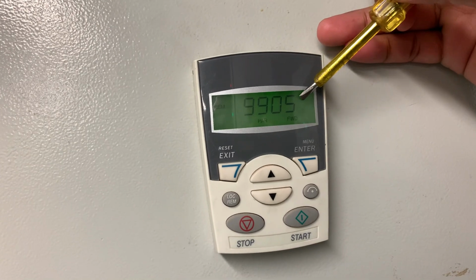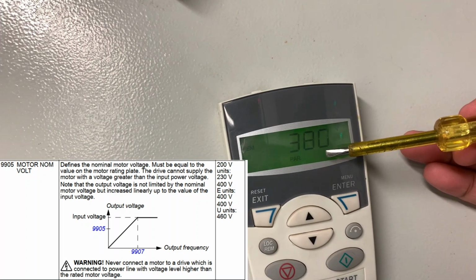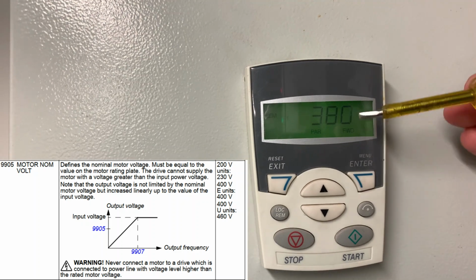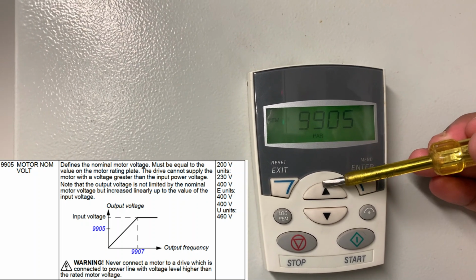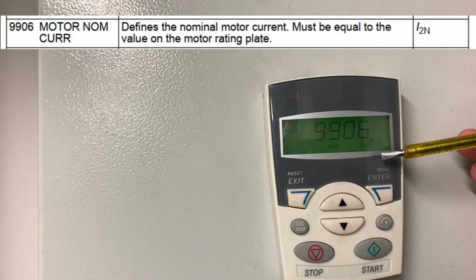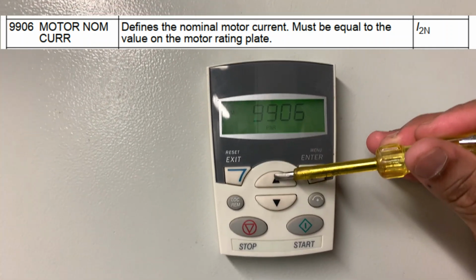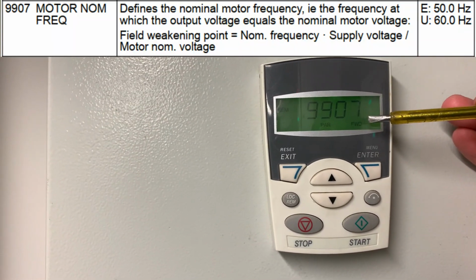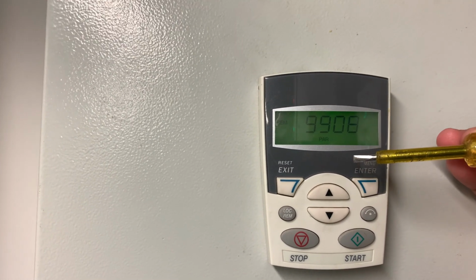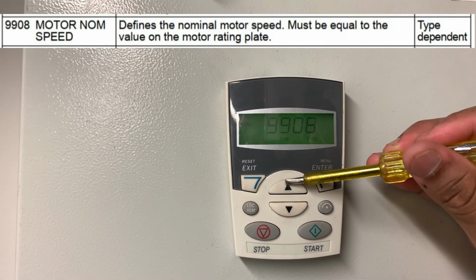Next, in 9905 you have to select the motor nominal voltage. In our case, you can see 380 volts, because our motor is a 3-phase motor and the input supply is 380 volts. 9906 is the motor nominal current. In our case, 6 amperes is the maximum current consumed by our fan. 9907 is the frequency, which is 60 Hz. 9908 is the motor speed, which is 1700 RPM.